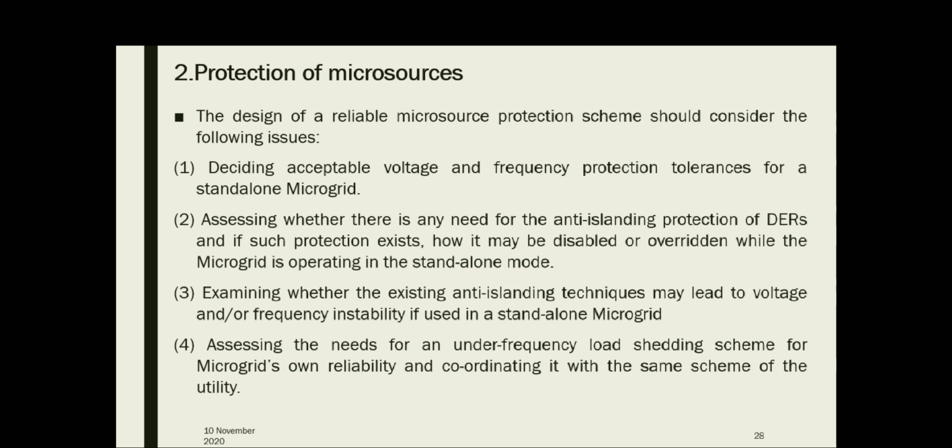Second is assessing whether there is any need for anti-islanding protection for DERs, or distributed energy resources, and if such protection exists, how it may be disabled or overridden while the microgrid is operating in standalone mode.